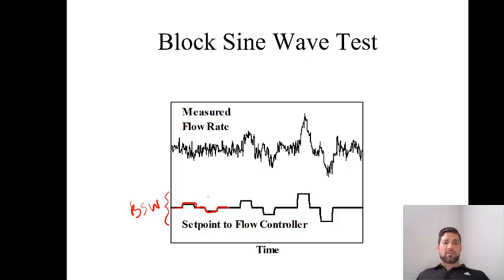If we apply a small enough step up and down, we don't expect our process to really change very much because all valves have a deadband. For small requested changes, we expect that to either stay within the noise or not change very much. As we continue, we do larger steps up and down in the set point of the controller. At some point when the step is large enough, we'll see the system respond a little bit outside of the noise.